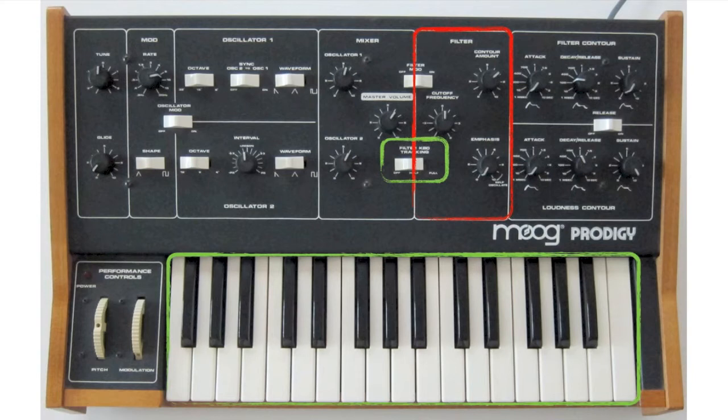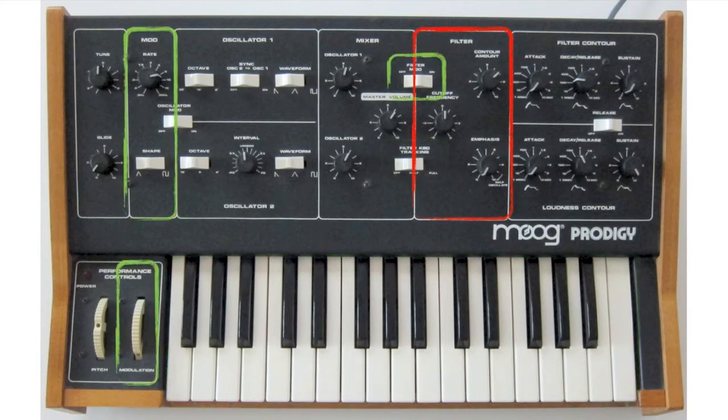The amount of modulation is controlled by the filter keyboard tracking switch, which can be set to off, corresponding to no modulation, half, meaning a modulation amount of 1/2 volts per octave, or full, meaning the full 1 volt per octave that the keyboard produces. Similar to the VCOs, the LFO can be routed to the VCF as a modulation source. This is controlled by the filter mod switch. The LFO's frequency, wave shape, and modulation also apply.